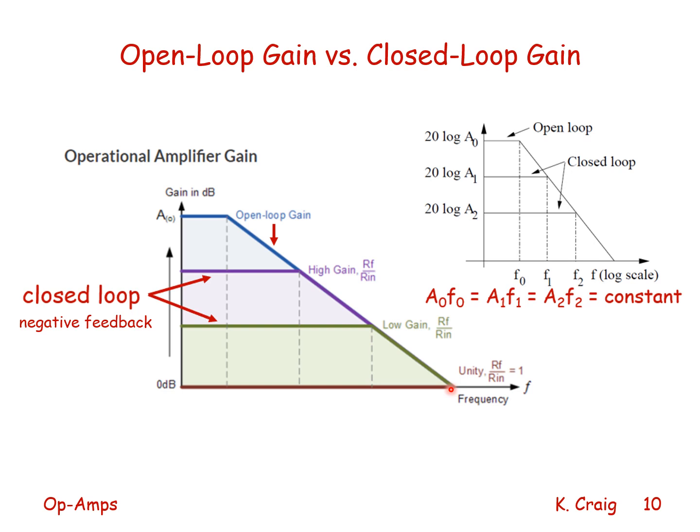In closed loop operation with negative feedback, the gain, whether high or low, and here it's shown for an inverting op amp with negative feedback, where the gain, as we will see, is the ratio of the feedback resistor divided by the input resistor. Here it is high, here it is low.